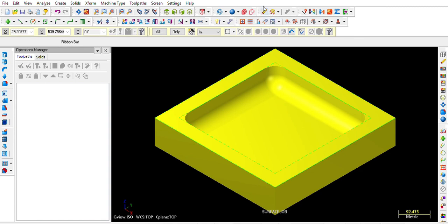Okay. Now delete all wireframe. So all wireframe models have been deleted. So now repainting this one would fetch me this particular object. Now I would totally copy this particular level, all surfaces, to the fourth level, where that will be my toolpath level. So level 4 digital.